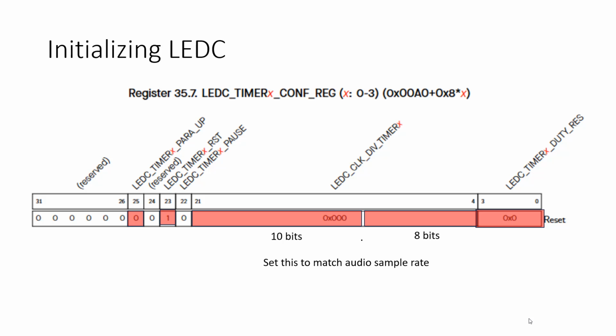So in your software, when I say your software, your ESP code, you're probably going to want to do that divide as a floating point calculation, right? But you have to convert it to fixed point before you put it in here. You guys follow me? So the way you can do that is you treat this like two different fields. This part is a little confusing because in the control register there's only one field, but really it's two. There's the whole part and the fractional part, right? And Alex's code explicitly puts both in separately, right? So Alex treats this as two fields, even though it is one field in the control register.